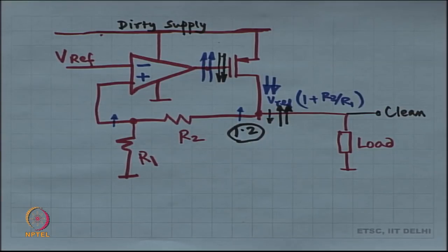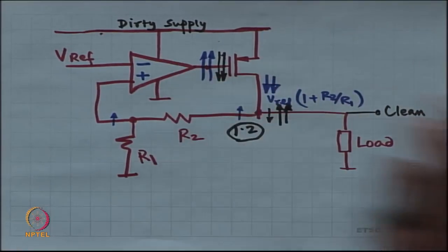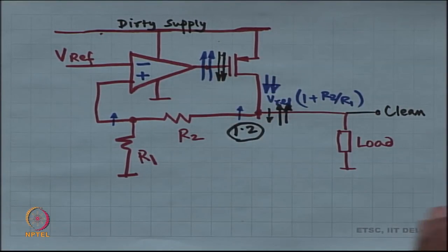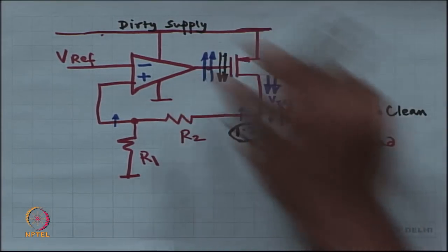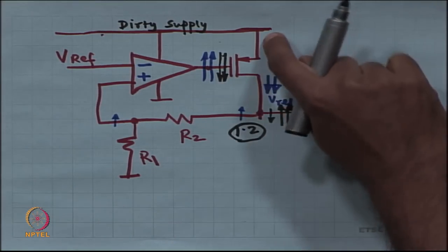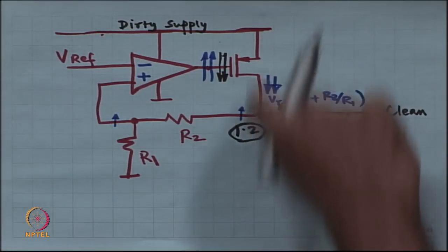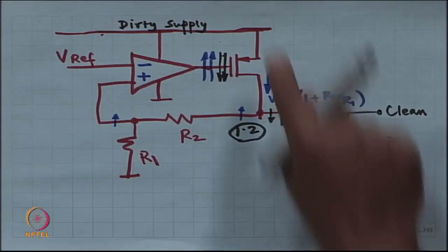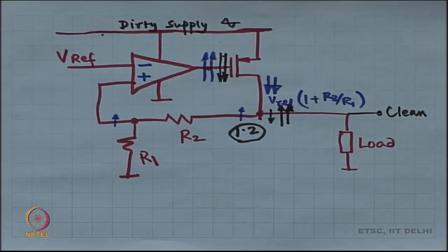No. Okay. For example, the drain of this PMOS can be higher than the gate voltage, it does not matter, as long as the drain to source is more than source to gate minus Vt. So, typical source to gate minus Vt, VGST, is typically 0.2 volts. So, therefore, this source voltage has to be more than 0.2 volts above 1.2, and then you leave some headroom for this dirty supply, right, another 0.1 volt.